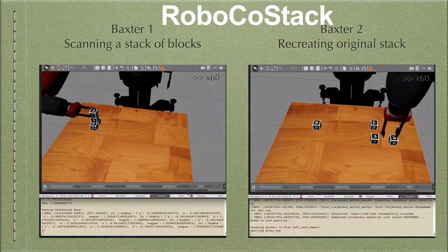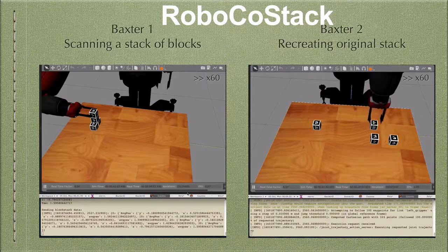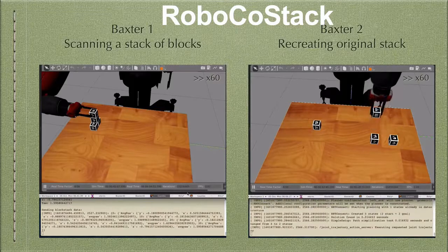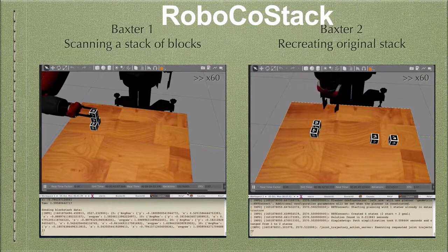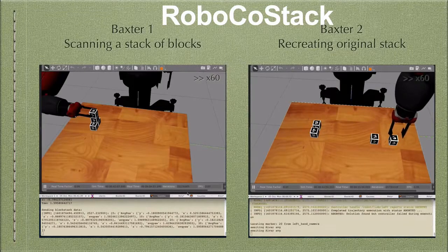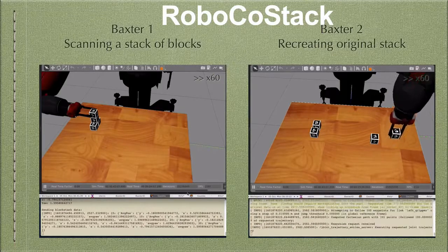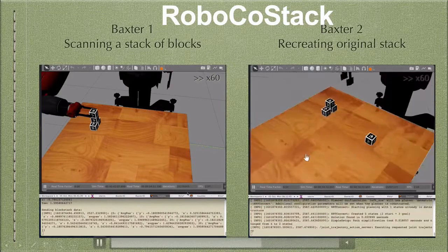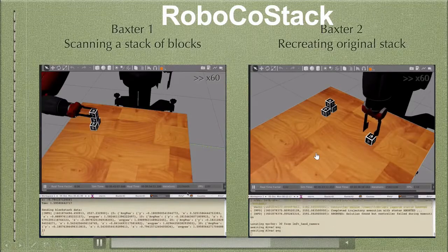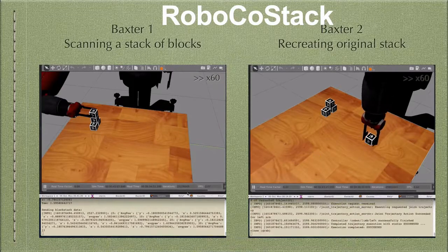Given that this scenario involves two remote robots which are effectively connected only virtually, it was possible to construct a simulation of the whole system by composing two separate Gazebo simulations, the scanning simulation and the stacking simulation, connected by a ROS feature known as remote topics.